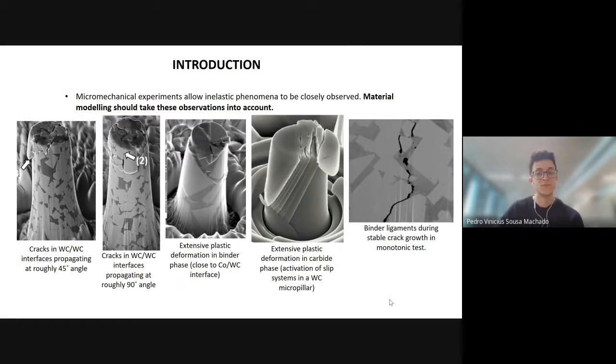So these are some of the local behaviors that we should also be able to observe in the simulations, because we not only want the simulations to coincide with the stress-strain curve calculated from the load-displacement, we also want similar qualitative results, in the sense that we want the same failure mechanisms to happen in the simulation. This tells us that the models are working.